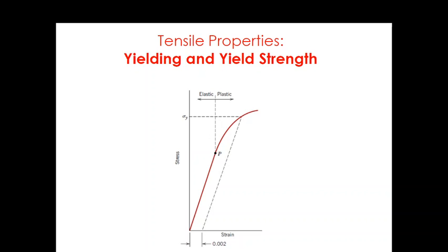It is therefore desirable to know the stress level at which plastic deformation begins or yielding occurs. For metals that experience a gradual elastic-plastic transition, the point of yielding may be determined as the initial departure from linearity to non-linearity.